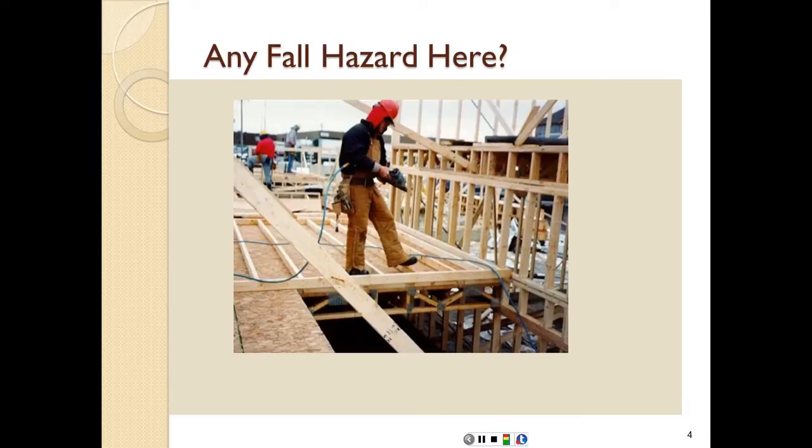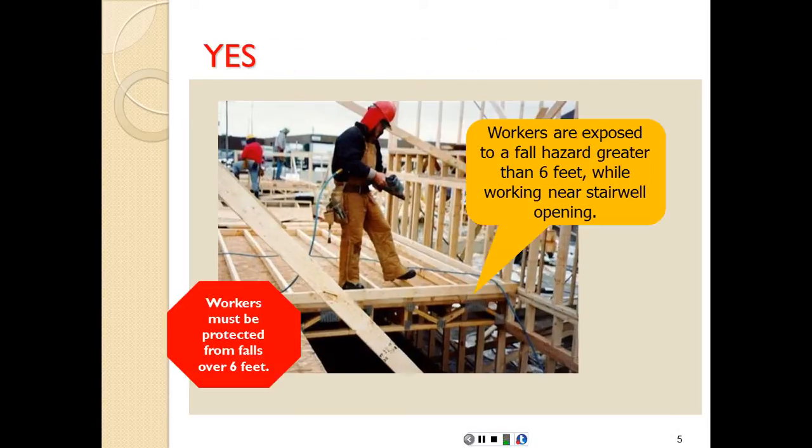Here's another example. A carpenter working on some formwork, and he's getting close to an open end, and he doesn't have any fall protection equipment. So again, we can see also the power cable around him for his drill, and if he trips on that cable, he might fall, and again, that's probably at the 2nd floor level, so there might be an injury here as well.